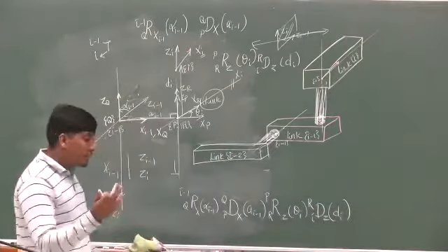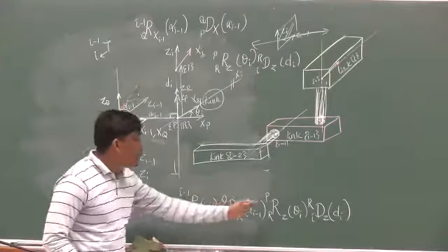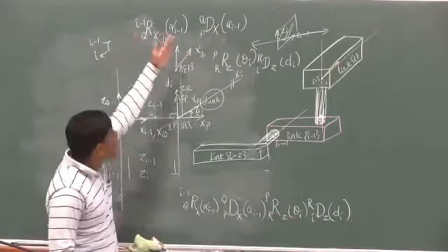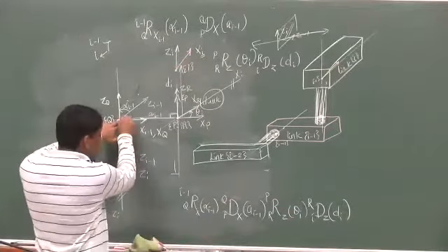If I see the earlier case, it is with respect to the moving frame, so obviously we post-multiply. That's why you can see I wrote individual matrices. Now I am putting them together. The first operation, I rotated this.